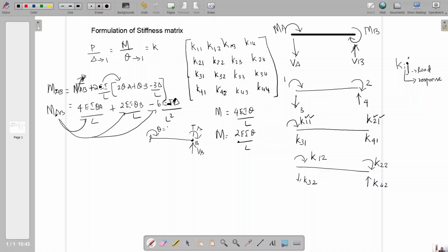If you consider A as fixed, you can have a deflection curve like this, and you can draw the moment causing the deflection like this. If some point makes a delta deflection, the moment will be created like this to make the delta deflection at point B, and at A the support is considered fixed because the other ends are considered fixed. So the moment should be formed like this to keep this support as a fixed one.